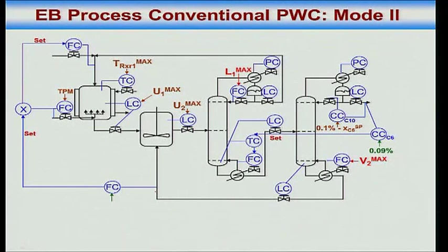I am preventing snowballing here by adjusting the ratio, and I am keeping the total benzene constant, right. So an impression gets created that there will be no build up in both the recycle loops.